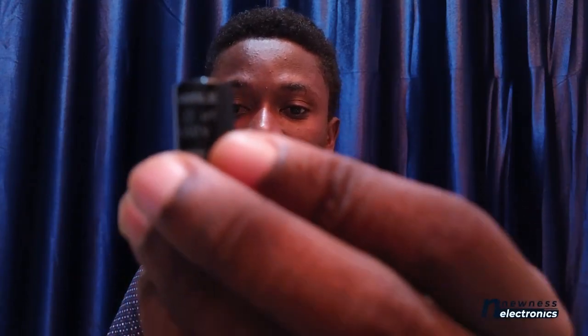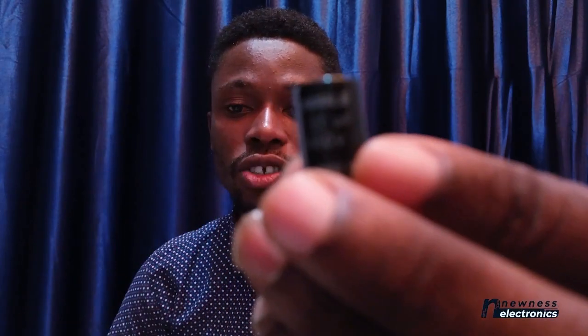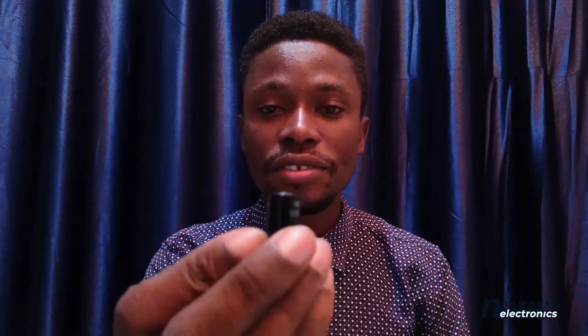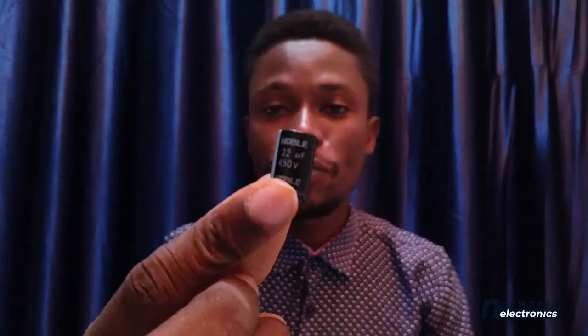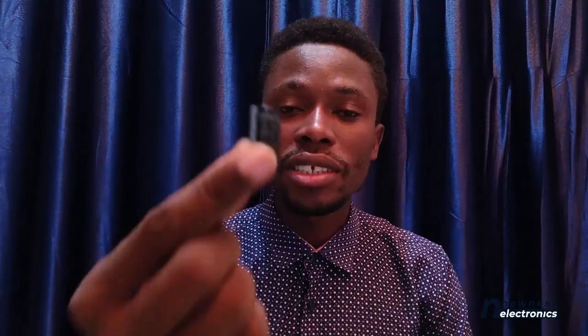Is there a lot of capacitance? Well, it depends on the application. And then the V there tells you how much voltage this capacitor can tolerate. So this is rated 450V. This is a high voltage capacitor. That means this capacitor can successfully withstand up to 450 volts between its terminals. That's a dangerous capacitor there. When you are repairing and you see such capacitors, don't just go ahead and touch the terminals. You can receive an electric shock from there.